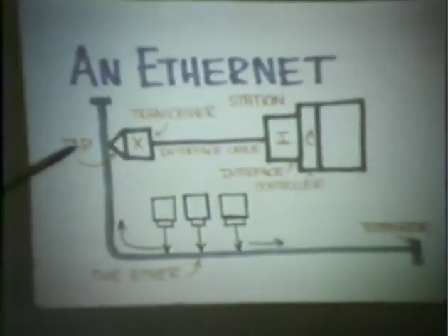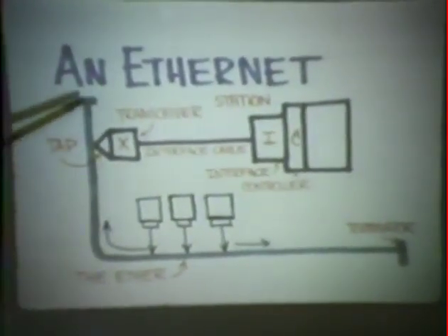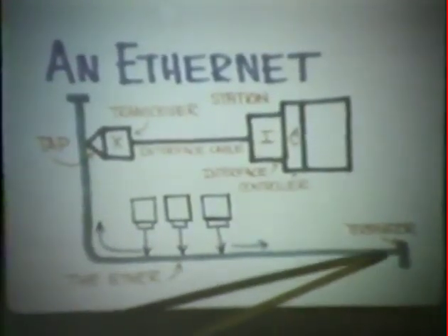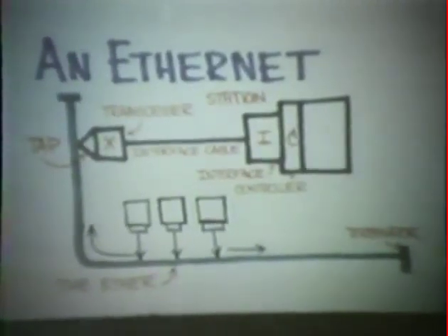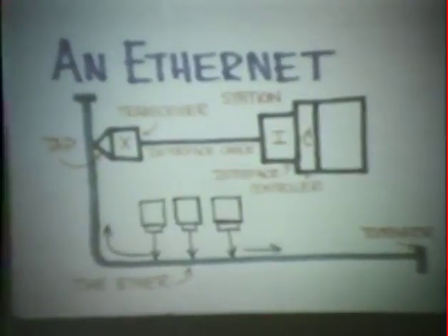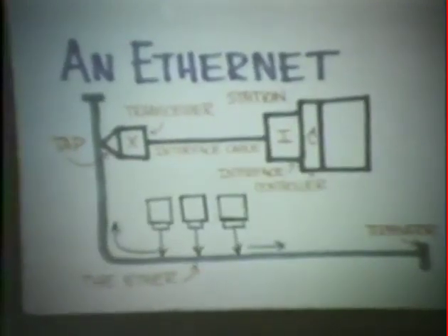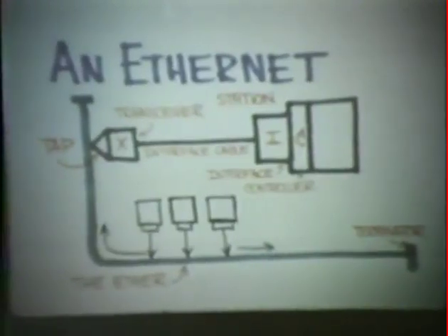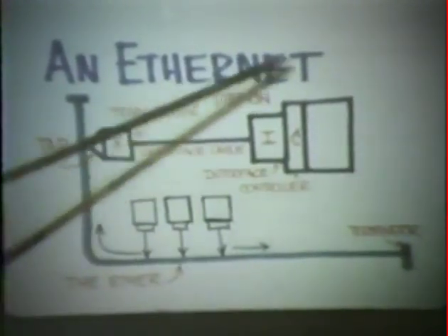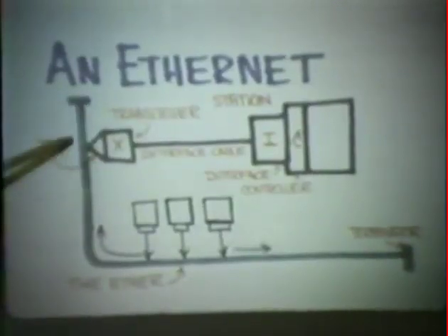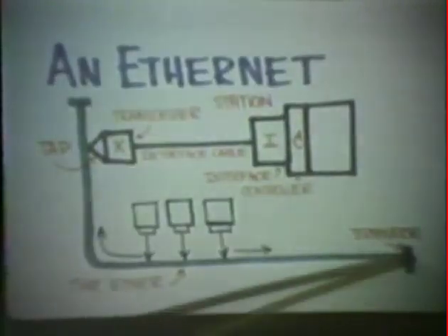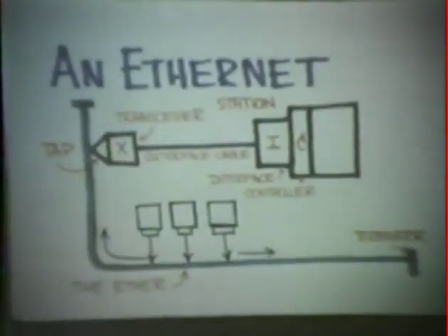This is at last a picture of the Ethernet, and let me run through it slowly. This heavy green line is the ether itself, which in our Ethernet is a 0.406-inch coaxial cable, RG11 style foam cable, for those of you who know about such things. This coaxial cable is terminated in two places at each of its ends. A station wishing to transmit injects its packet into the cable, and the packet propagates through the whole cable, finally burning itself up in the terminators at the end.